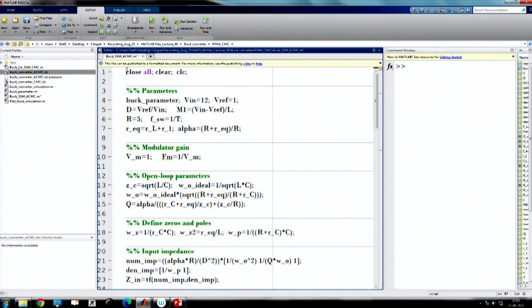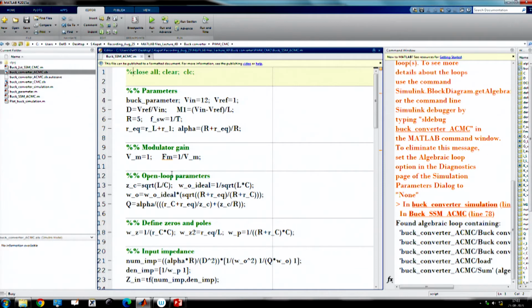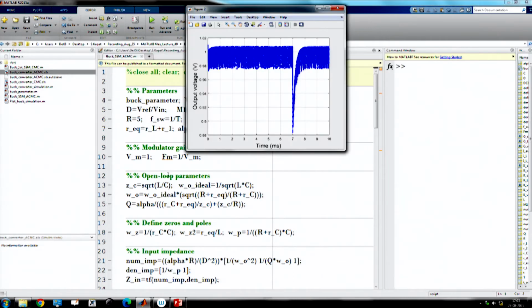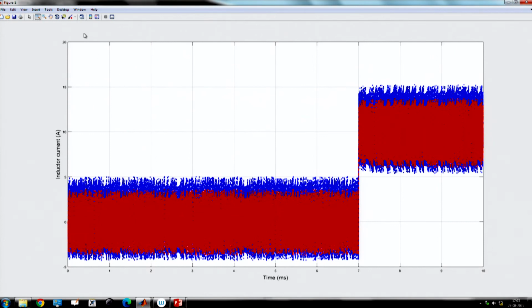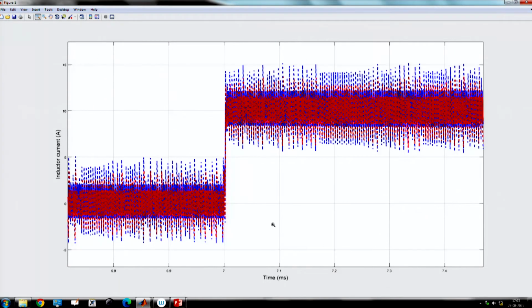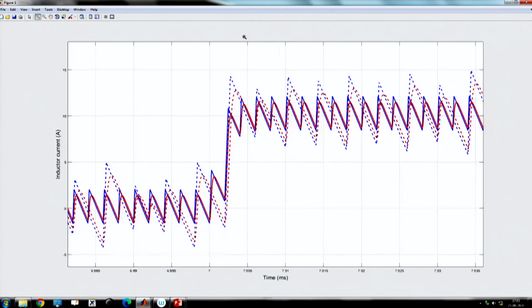So, now we are taking same as the switching frequency. Okay. So, what I am trying to say, still it is unstable, because I have set the voltage loop bandwidth to be almost 1/6 of the switching frequency, 1/5 to 1/6.